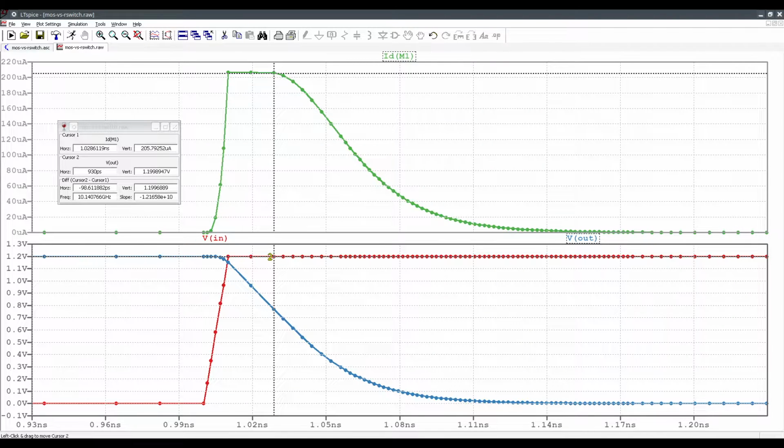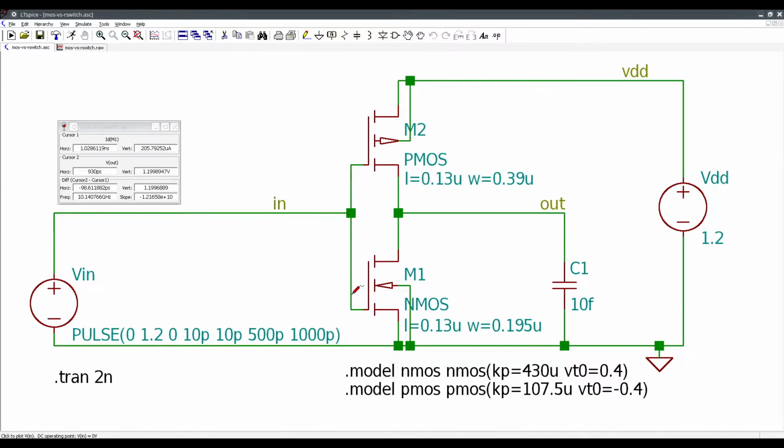My drain voltage, go back. So my gate voltage is red. My drain voltage is going from high to low. This is 400 millivolts. Well, if we look, the gate is 5, the drain is 400 millivolts below that. So at that moment is the threshold voltage.